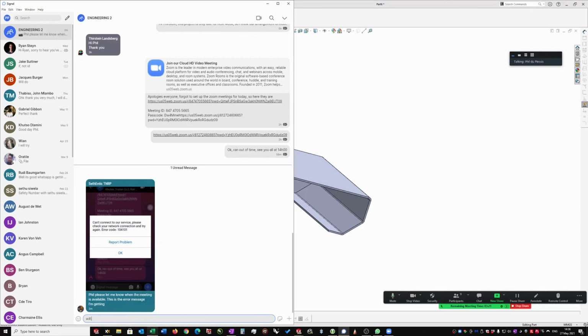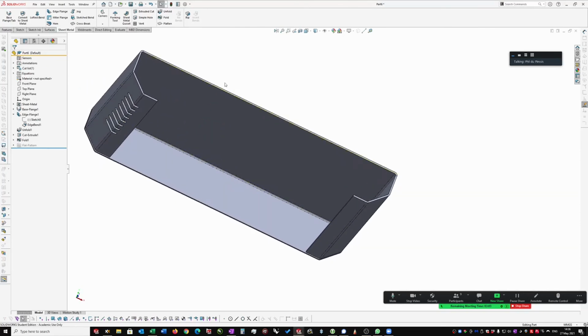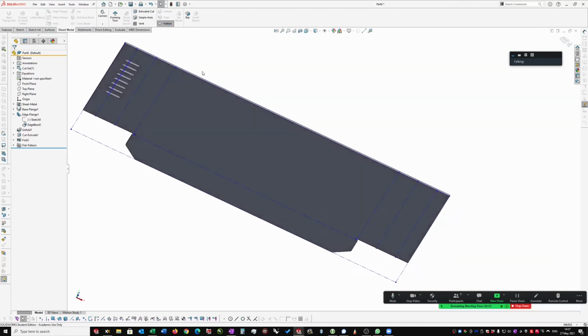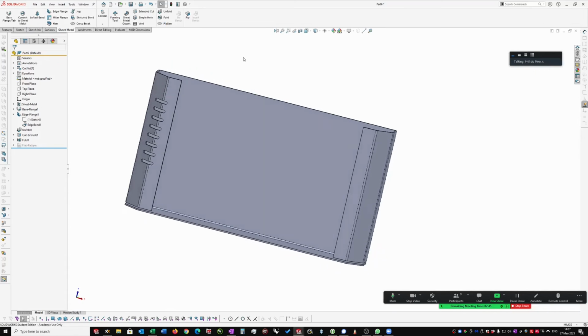Would we need to put those cuts into the design now already? Yes, I'm going to ask you to put cooling vents into the design. All right. It's not too difficult, I hope, as long as you follow the sequence: unfold, then do your cut, then fold again. Whatever you do, don't use the flatten one as the basis to put a cut in. It won't work. The flatten is just a visualization tool. It doesn't do anything else.